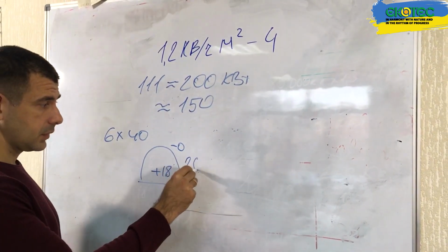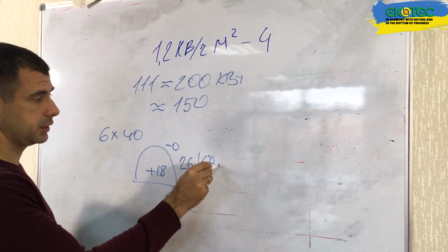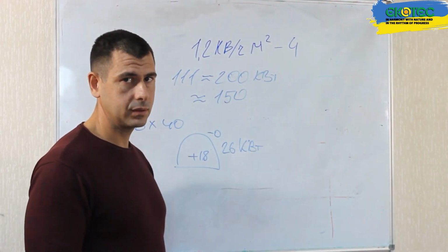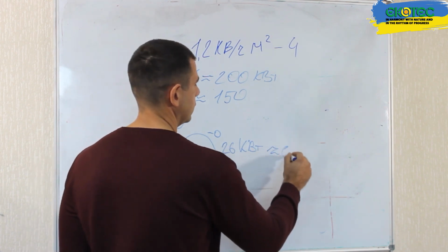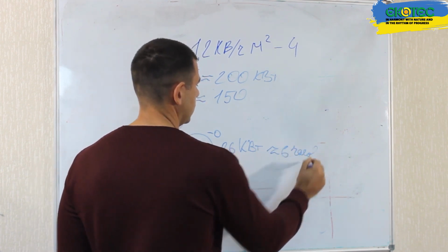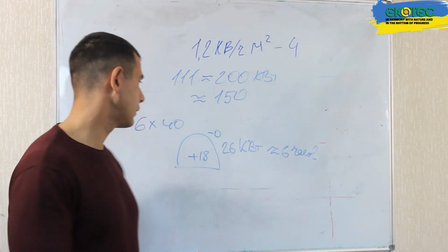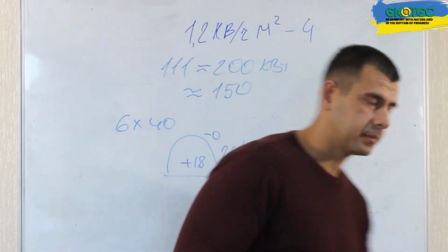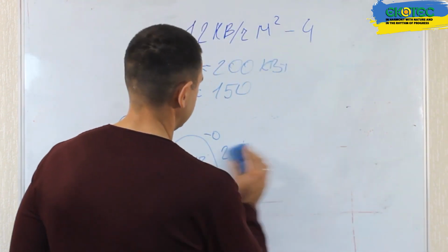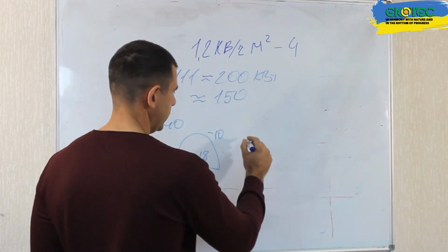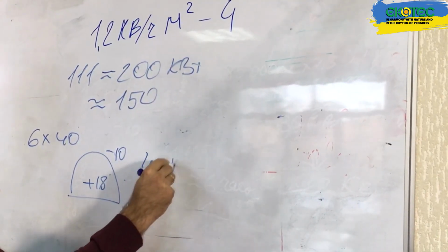In summary, while the greenhouse can't rely solely on heat accumulators for heating during winter, it can provide a significant boost. For example, on the coldest day, we can accumulate at least 111 kilowatts. However, if it's 25 degrees outside and the sun sets, we'll use up this accumulated heat in about 2 hours. Therefore, we need to restart the boiler, but we have 2 hours of free energy.